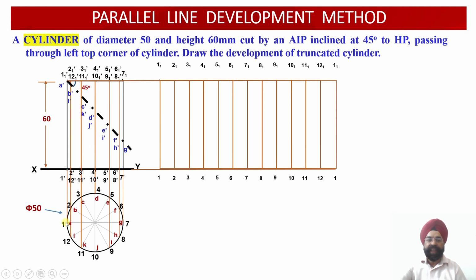Rather than measuring the arc, we measure the straight line distance, that is the chord length between these 2 points. So these gaps which we have shown over here are marginally smaller than the actual lengths which should have been there. So the cylinder, or the length which we obtain using manual drafting, will be slightly shorter.